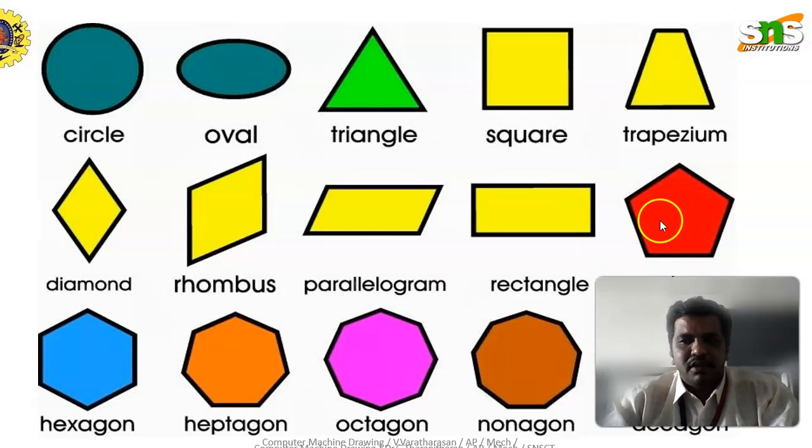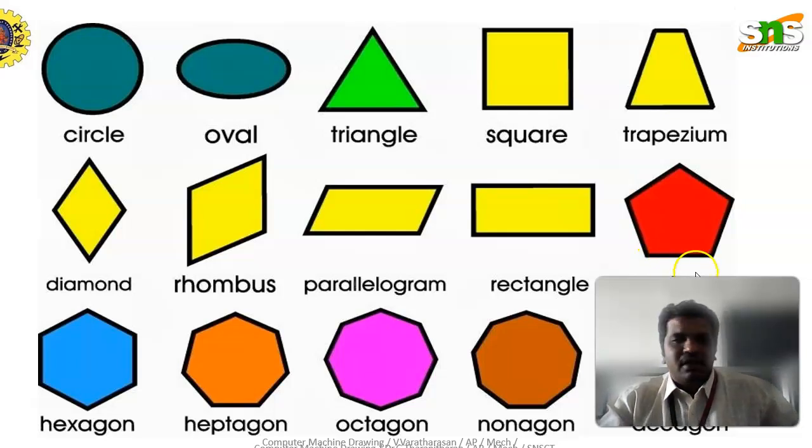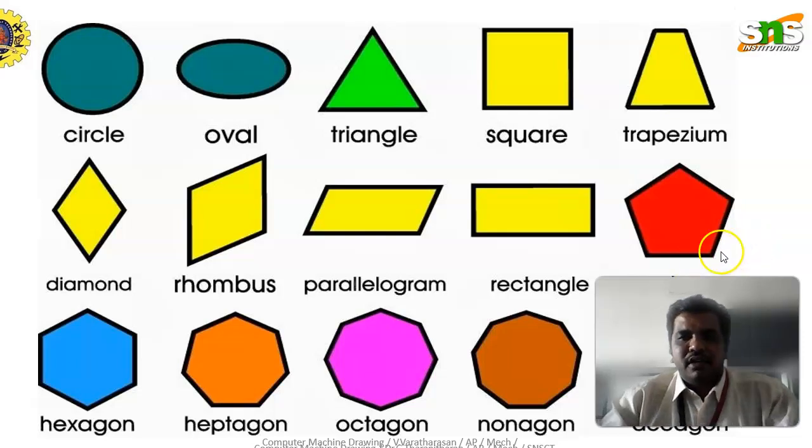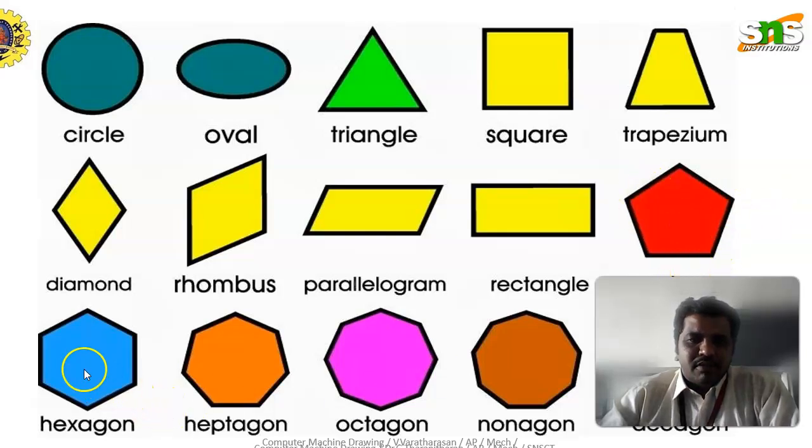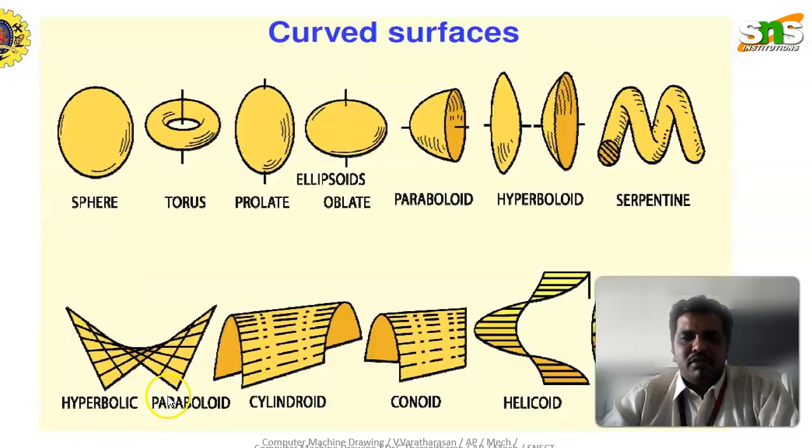If you are going to draw the pentagon, the plane or lamina sheet, whatever it is, through the pentagonal shape, we can't draw it directly with respect to the base side dimension. So by using the base side dimension and also the 108-degree inner angle, or the external angle of 72 degrees, we take the angle of representation. On the angled line, we can measure the particular baseline length. Then by using a compass or divider, we can represent the particular measurement in the pentagonal shape. It is the same for the hexagon, where the proper procedure is also available.